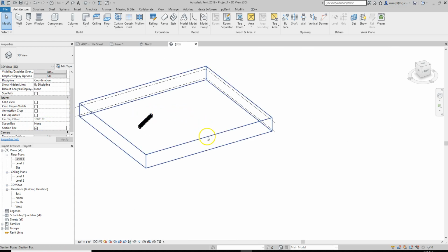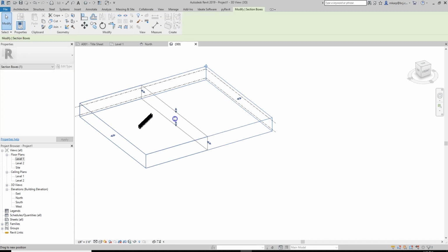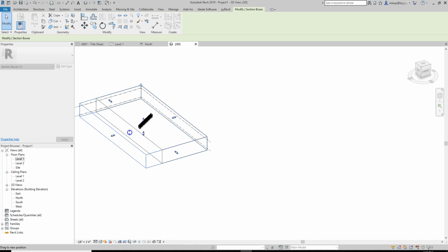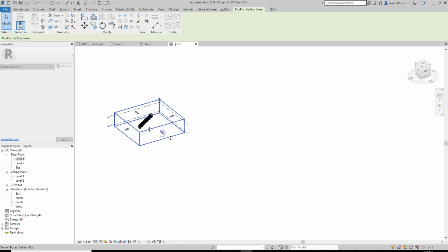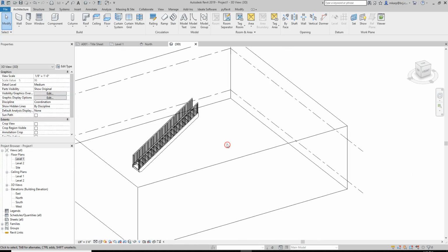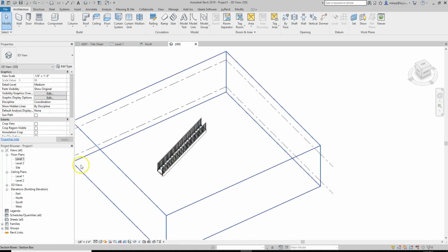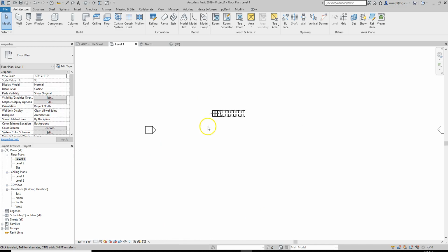So I just want to take you through some other steps on making a run staircase, especially one that might have a landing in it or turn around on itself. So let's just section box this down so we can rotate better. Right next to this I'll make another staircase. Same process: Architecture, stair.